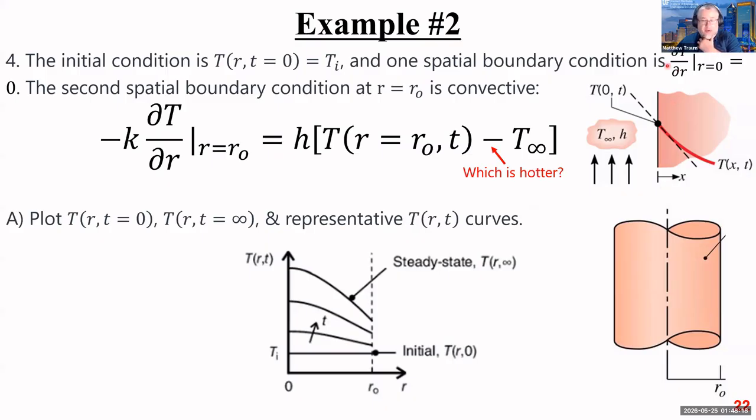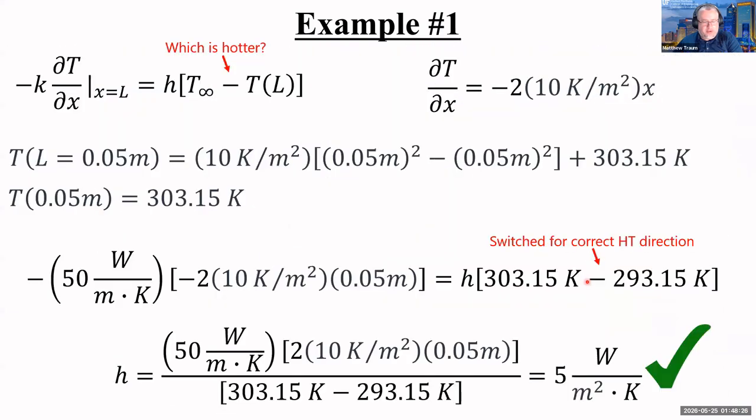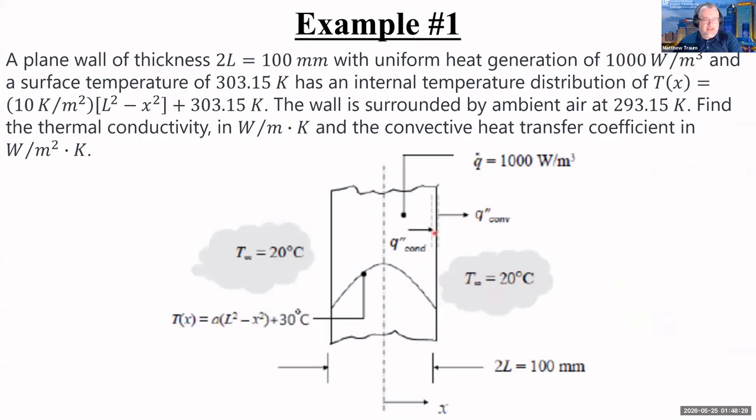We talked about it a little bit when we were going through the lecture, but let's just think it through. And in fact, I'm going to cheat here a little bit. I'm going to go back to the previous problem. I recognize that this is not cylindrical coordinates, but this gives you a sense of what that temperature profile potentially looks like, because this is a similar problem in XYZ coordinates instead of polar coordinates. But look what happens right here. Right at the center of the slab, the first derivative of that temperature is 0, because it's symmetrical from 0 to positive x and 0 to negative x.